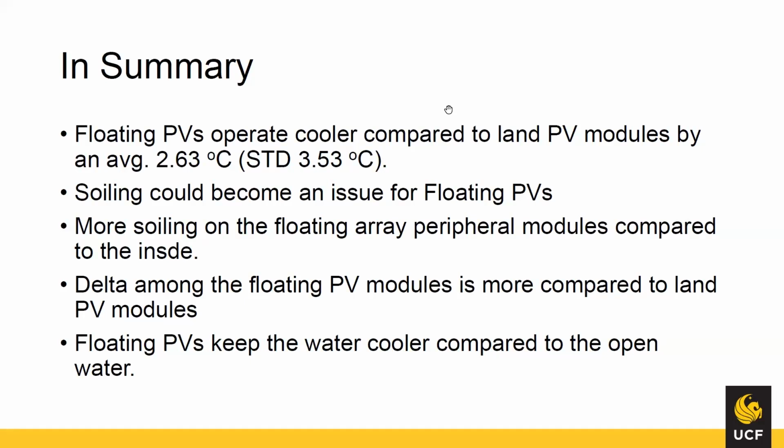Yes. Excellent. They didn't have the answer yet on what the temperature coefficient of the panels was, because you'd have to know what the panels were, since it's going to vary between panels. They all have a different temperature coefficient, so that would look at the energy output of the panel based on how much cooling there was in the water. So we can get that if we find out what the panels are that were used at the site.